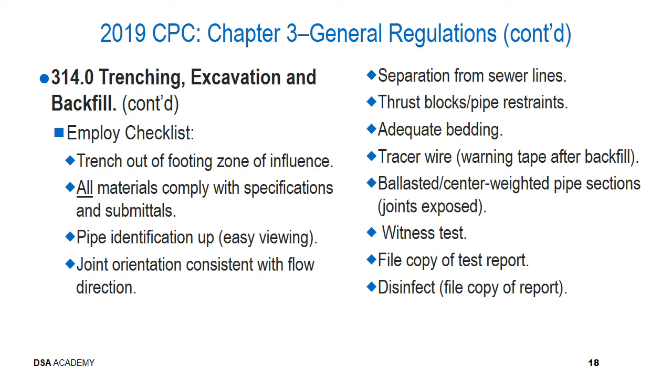So with respect to the checklist, number one, I would recommend that all project inspectors, again, employ a very logical process. Logical meaning from the bottom up or from the beginning to the end. What I mean to say is there are materials that are installed in that trench. You do not have to wait to inspect the materials until after they're installed in the trench.